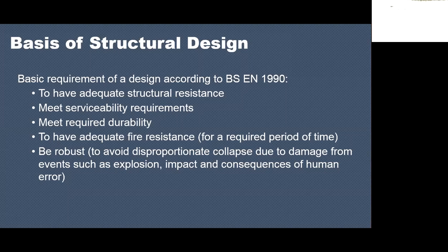And it should have adequate fire resistance, and it should be robust to avoid disproportionate collapse due to damage from events such as explosion or impact and consequences of human error. For example, if you have a bridge and a big truck hits a part of the bridge, the bridge should withstand that impact.